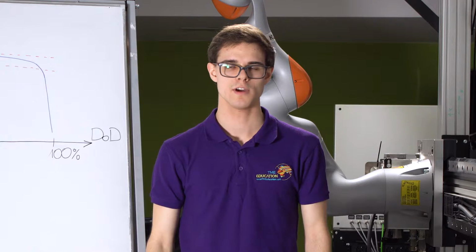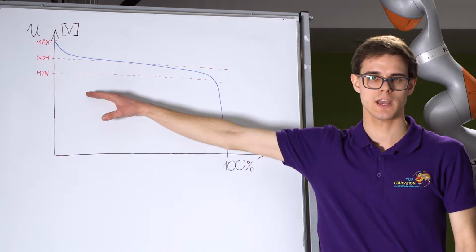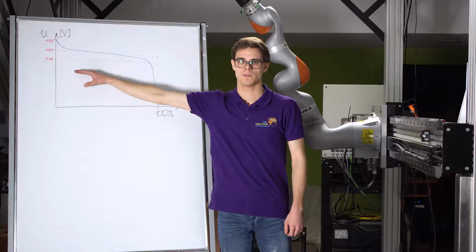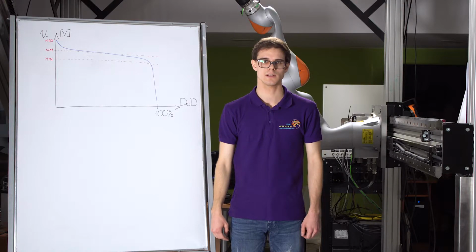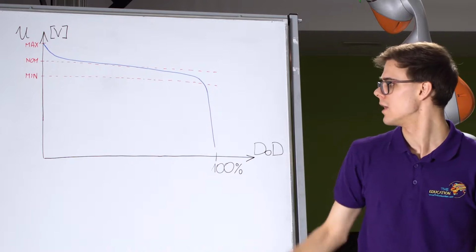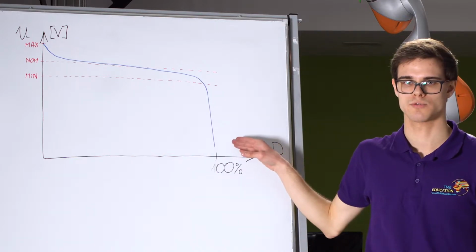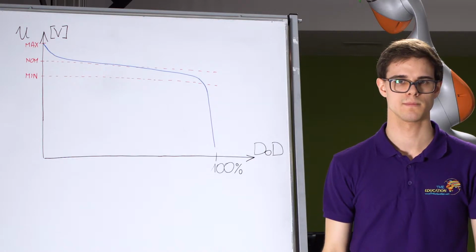It is worth knowing that electrochemical voltage sources do not have constant voltage for the whole time of their operation. When the battery is fully charged, the voltage is slightly higher than nominal. During operation, the voltage slowly decreases until the battery is discharged. If you discharge it further, there is a sudden voltage drop, after which cells are damaged and the battery becomes useless.